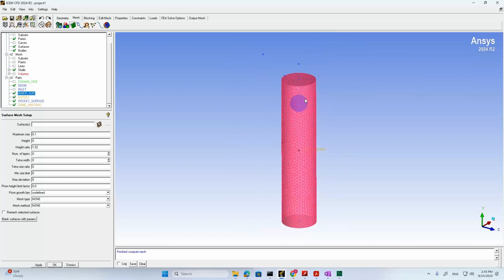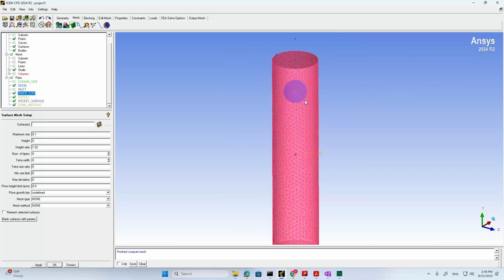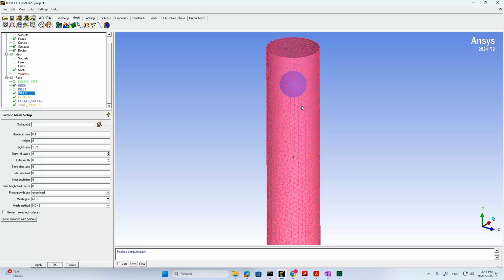But for me, if I want to find a way to get around it, I will add an even smaller cylinder around, or maybe even a sphere shape surface to enclose my rocket, and I use a really fine mesh inside that small region. Okay, that is what I can do.